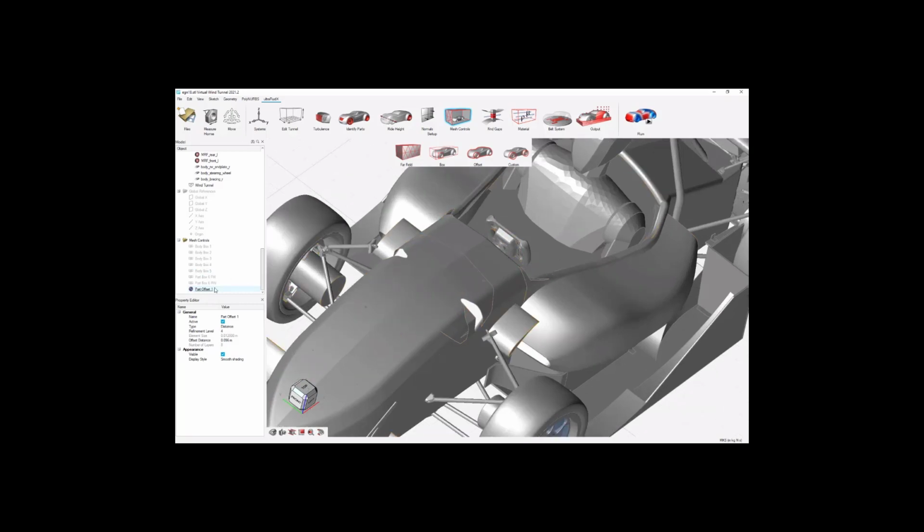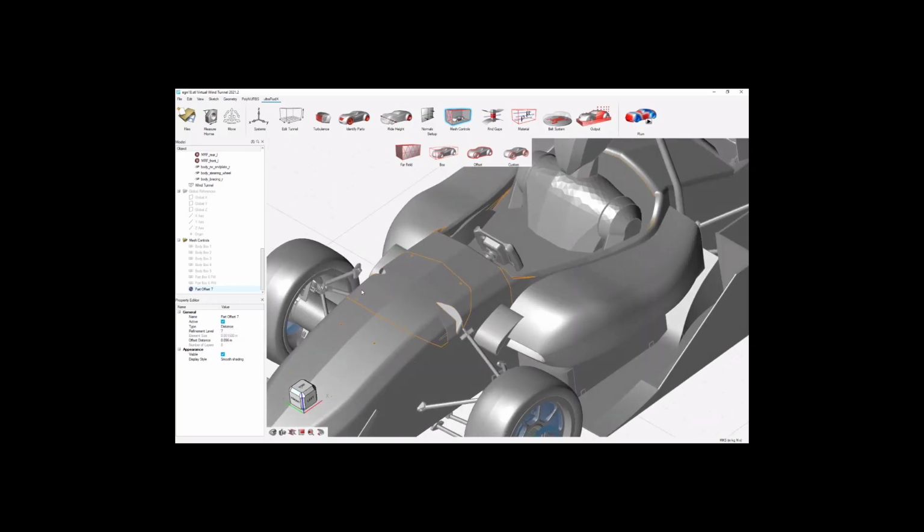So to specify it, let's click here. First change the name to refinement level 7, so part offset 7. I want it to have refinement level 7, of course. And here you can choose the offset distance. So for example, a distance of 0.096 meters would result in a number of 8 layers. So the first 8 voxels closest to the surface of the wings will be refinement level 7.